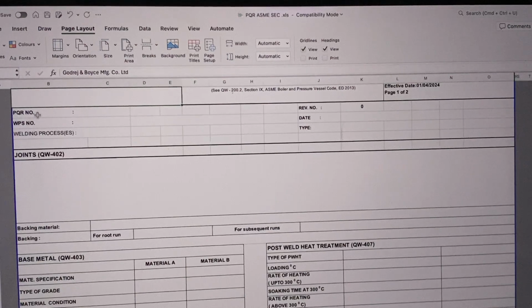That means whatever we have planned in the WPS, is it going to meet the specifications and requirements of the customer, and is it going to meet our internal target as far as achieving the non-destructive test or NDT results, the distortion levels, the surface finish, machining allowances, or the tolerances as welded and post weld heat treatment? Are we meeting them or not?